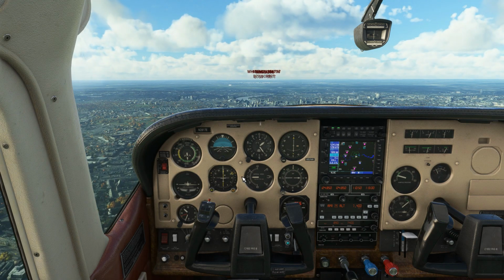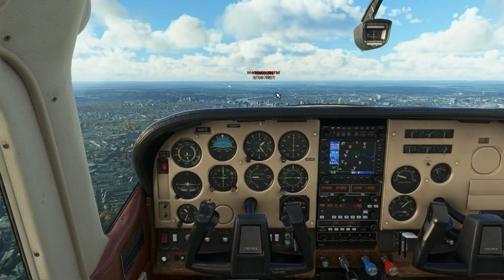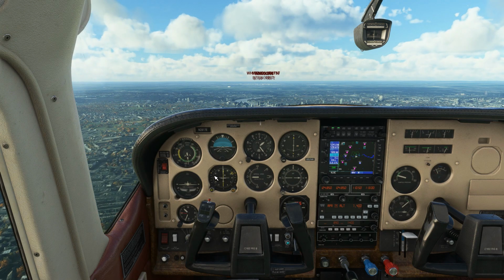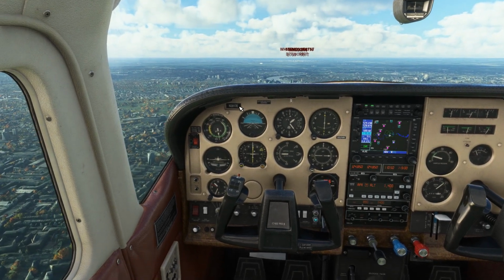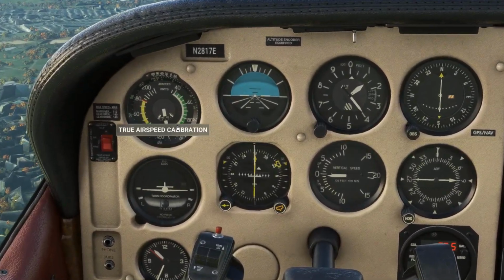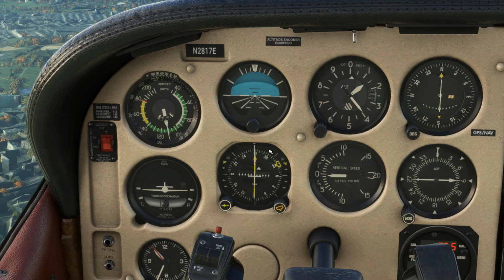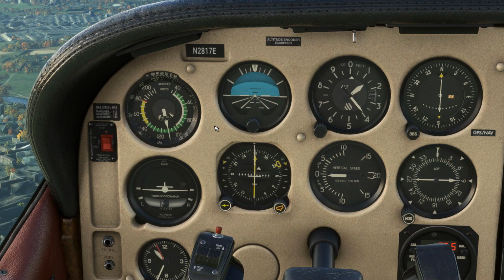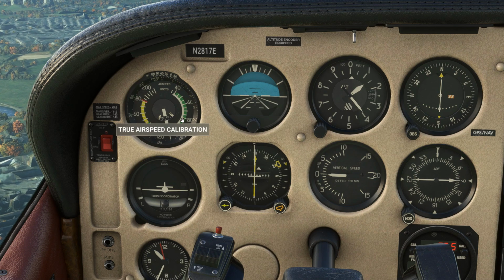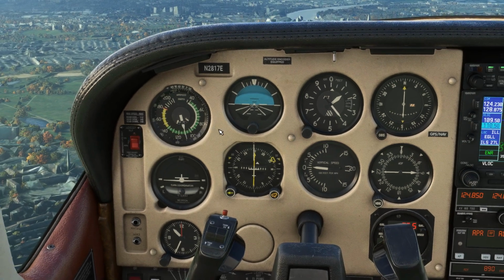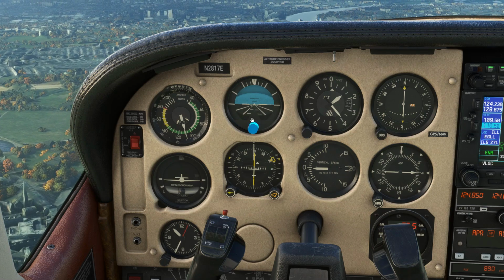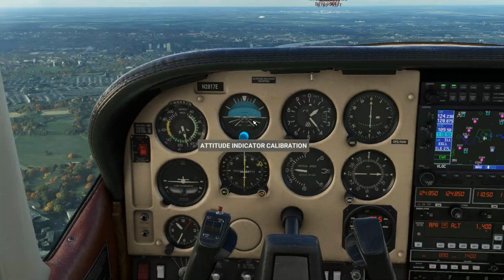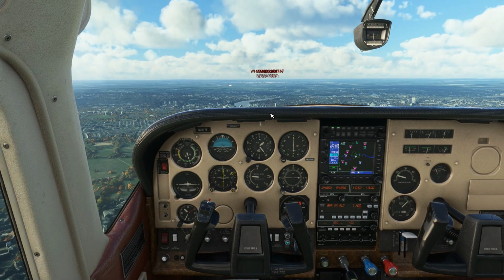And once I feel I get a little bit closer to Heathrow Airport, I'm going to slow us down. And again, it's getting to know your instruments. I'm going to slow us down to this white ribbon, as you can see on the speed there. So you can see that white ribbon. Get us so it's just below 100 knots. And then I can properly, shall we say, go to stage 1 flaps.